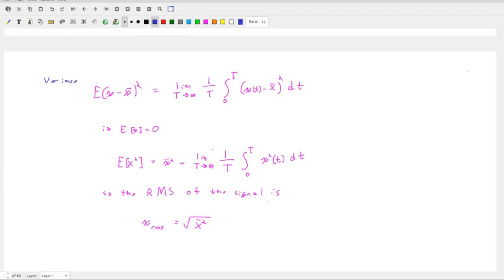It's a sinusoid. So the mean's going to be 0. Your maximum voltage at the wall is about 170. Yeah, it's the RMS. So that 120 is the root mean squared of your signal, because it's going in and out, in and out. So its mean is 0, its max is 170, but for some reason we take the RMS as the value. So 120 RMS is what's at the wall.